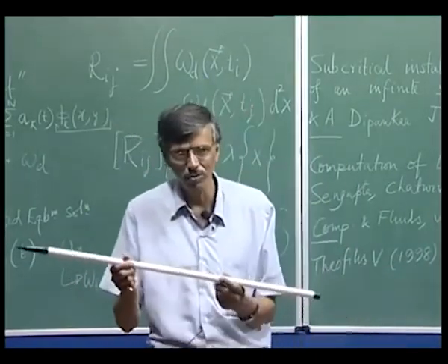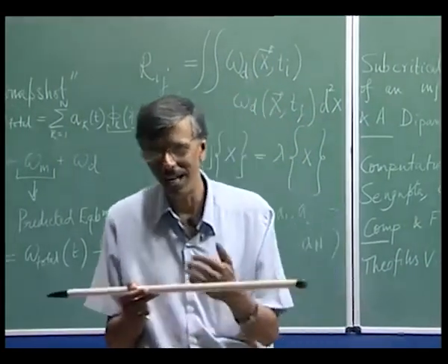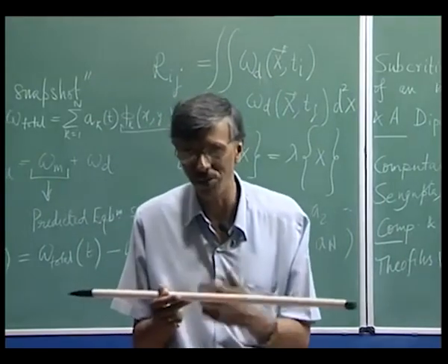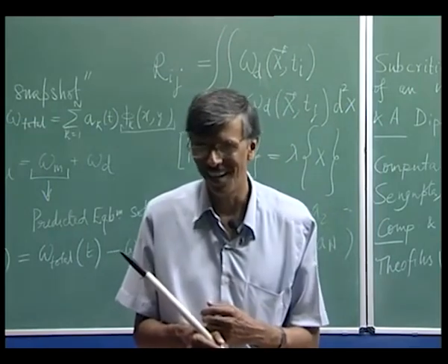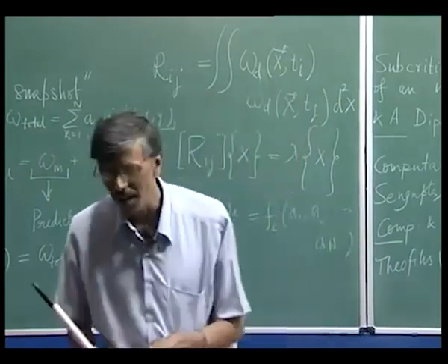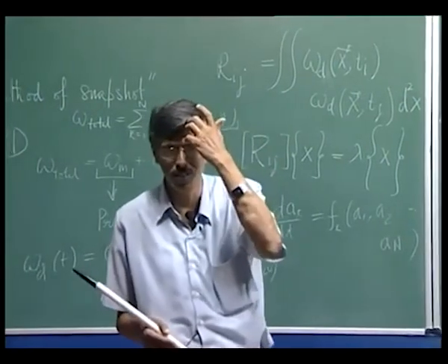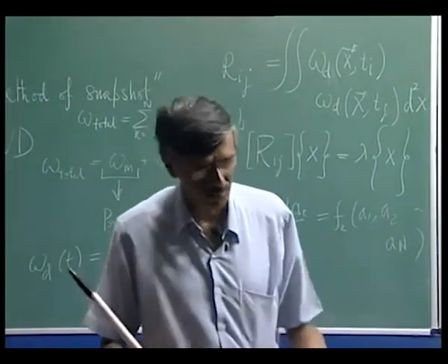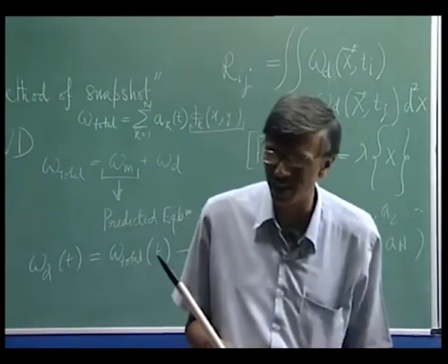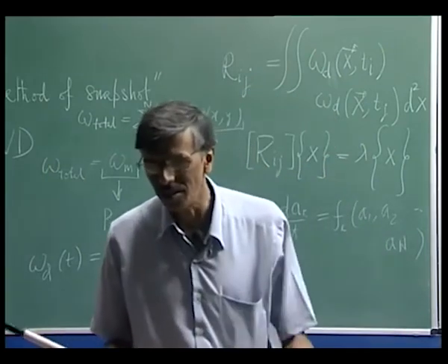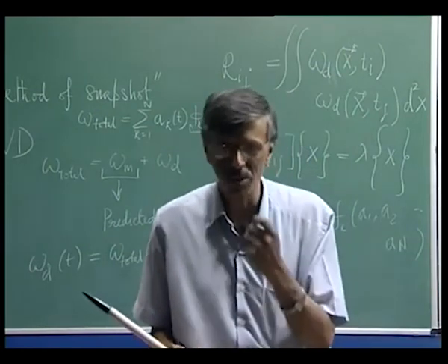But when the wing was swept back, people noted that the flow transition occurs over the wing where you actually have favorable pressure gradient, not adverse. This was a very confusing thing. Time permitting, we will come back and talk about streamwise and cross flow instability of three-dimensional flows past a wing. People have now gotten some understanding of what causes three-dimensional flow to be qualitatively different from two-dimensional flows in showing these instabilities.